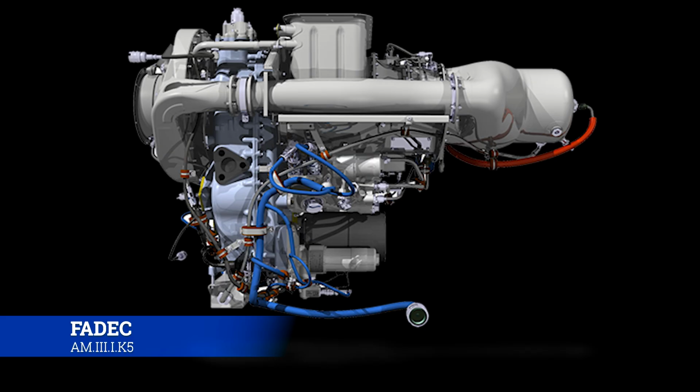Now, what is the difference between a hydromechanical unit with an ECU or EFCU and a FADEC engine? Well, in a FADEC engine, there are no mechanical linkages. It's literally electronically controlled valves that open up and close and do all the fuel metering that needs to happen electronically, without any sort of throttle linkages or anything else like that. Now, because of that reliance on electricity, there is a component with FADEC that has to be there that otherwise wouldn't be there on normal run-of-the-mill hydromechanical unit engines.